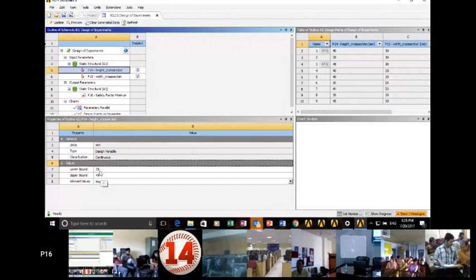I had set its value as 40, so I'll alter that value from 35 to 45. So I have entered 35 as my lower bound and 45 as my upper bound. Similarly, I'll change the width of the cross section. I had entered the width as 30 initially. Now I'll alter that value from 25 to 35.